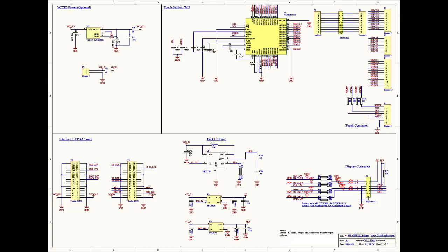Now getting back to DCS command processing, you can see here on the display after a few lines the color changes. It's because the FPGA has sent a command to change the address mode, but at the same time the FPGA keeps on sending data, and somewhere in the middle of the display content the LCD has processed that command and changed the addressing mode, which has ultimately turned green into blue. This kind of thing you should avoid by having an appropriate delay for the appropriate commands. Only a few of the DCS commands need certain handling.